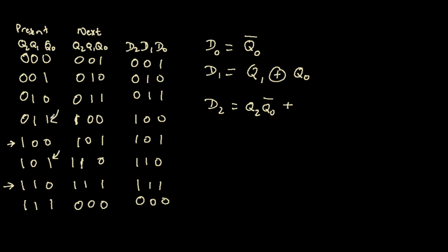Yes, it seems like there is a pattern. For one thing, for the other 2 states, your Q0 is definitely 1. And then what else do we see? We see an XOR relationship between Q2 and Q1. So is there any other state where you have your Q0 being definitely 1 and you have an XOR relationship between Q2 and Q1? Let's check that out.